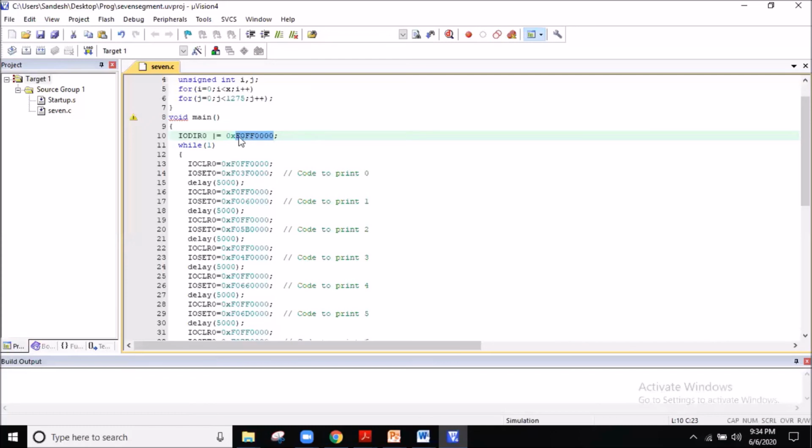If we consider the DP segment, then the register configuration is 0x followed by F0, where this F represents displaying the numbers on all the four hexadecimal digits, then we have 0, then double F represents the 8 segments which need to be activated to display the characters.